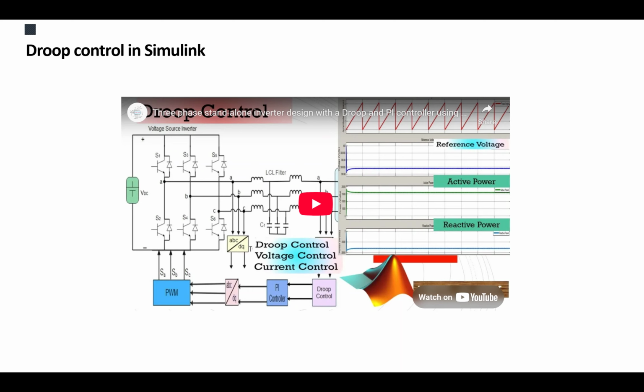Now I also posted an assignment, a reading assignment, basically. We all said that grid following inverters cannot work independently, and a weak grid scenario would have an instability situation. Now we want to solve the grid with grid forming inverters. We're going to introduce synthetic or virtual inertia, and we are going to solve the problem. These are the standard understandings. To be honest with you, I do not believe that grid forming is the answer to those problems.